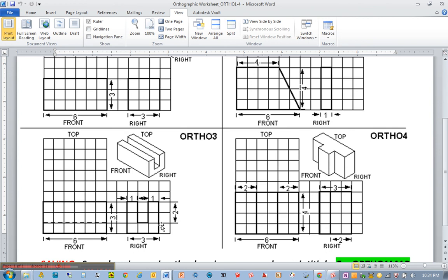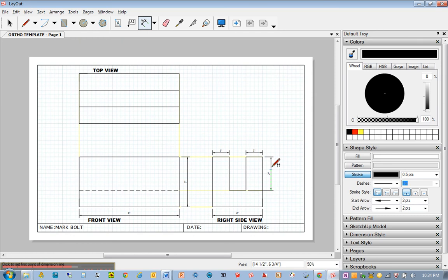It's kind of hard to tell here on the drawing, but if I were doing it, I would probably do it like this, and like this. Okay? We have enough information here in these 2 views that we could figure out what these dimensions are even without putting any numbers here. So there's no reason to over dimension, because if I do this, I already have the same information here. Okay, good luck.